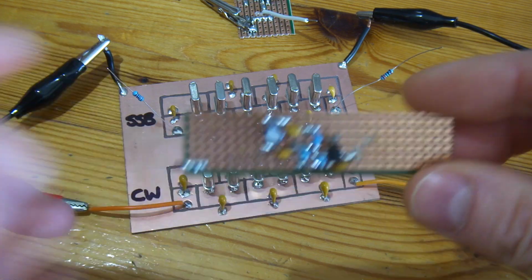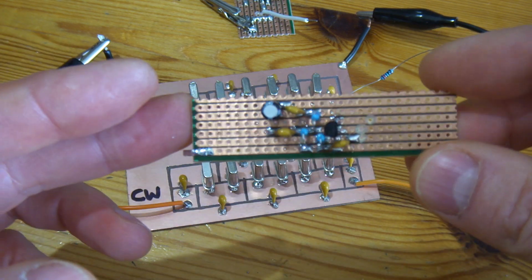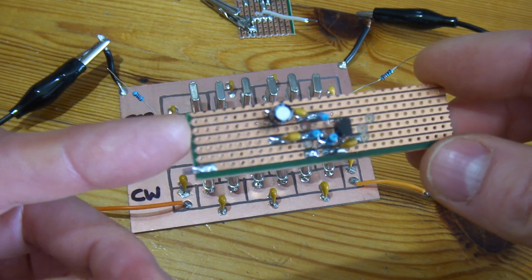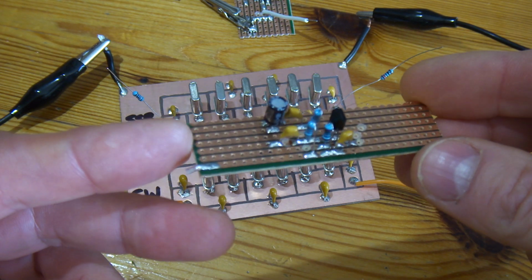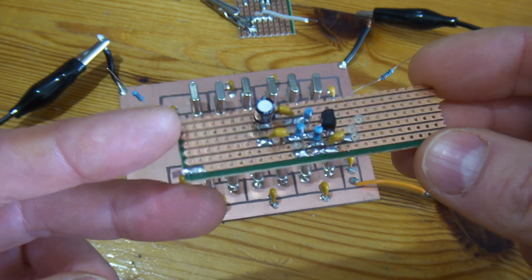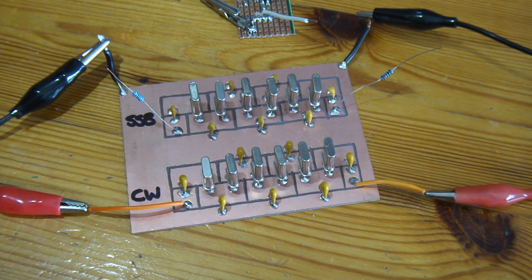And the same approach on the input. I'll mathematically work out what the input resistance of the stage is, and what I may even look to do is compare the mathematical calculations with a test measurement using, say, the Nano VNA. We'll see how close that is. Anyway, so that's going to be the next stage.